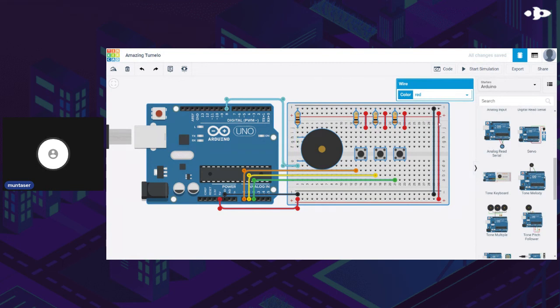One thing you might notice is there's a color combination. This is really good. It's not required, but it's really good practice, so that if your wires turn into wire spaghetti, you'll still know what wire does what. There's a separate color for every separate function, and the standard is using black wires for the grounds and red wires for the power.